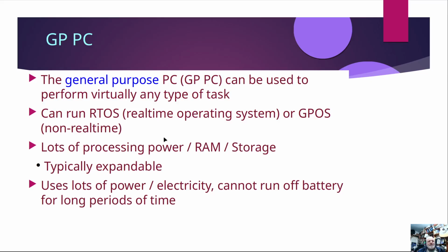Those are the things we've seen 100 times, where you're sitting there doing something and then all of a sudden it seems like the computer is taking forever to respond to you. But if you're running a real-time OS, you can set priority on certain tasks and be guaranteed that those are not going to take a holiday, but guarantee that they will be processed within a certain number of milliseconds.